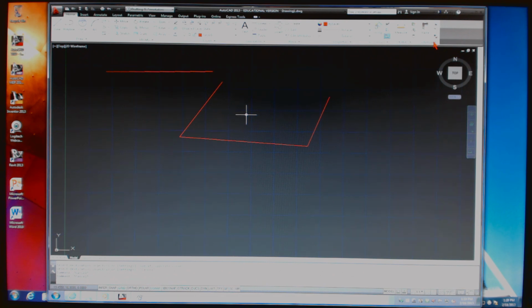Let's go to 21-4 in your book. We call it the Rev cloud, also known as the revision cloud. This is something that, as a draftsman working in the industry, you will have to use. Revision cloud is for once a drawing has been put out for bid. Supposedly it's 100% complete. Your company signed off on it, you sent it out, and contractors are getting it and putting bids on it, how much they're going to charge to build a certain portion of it.